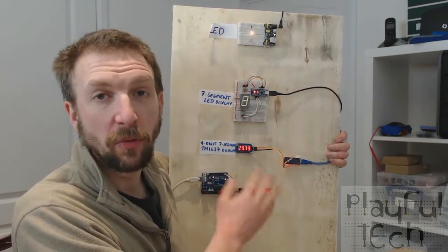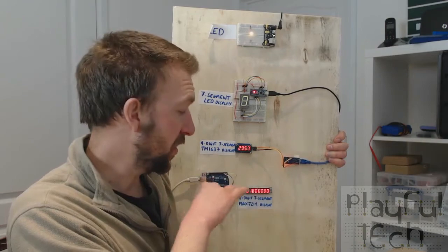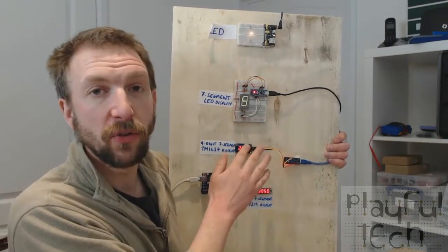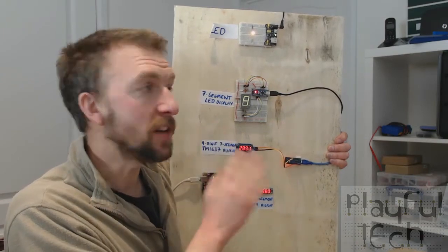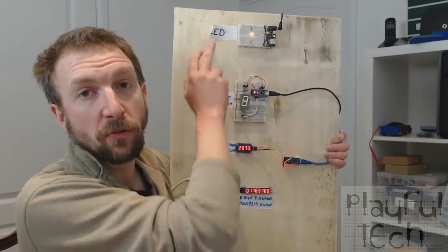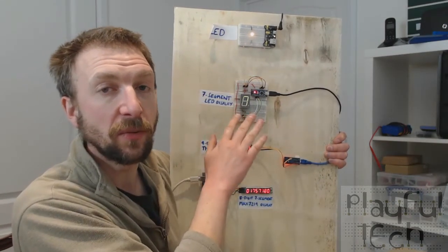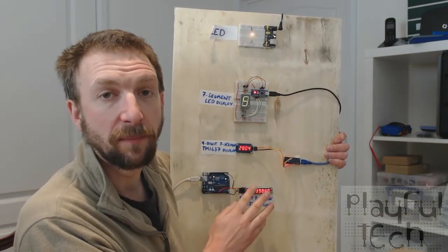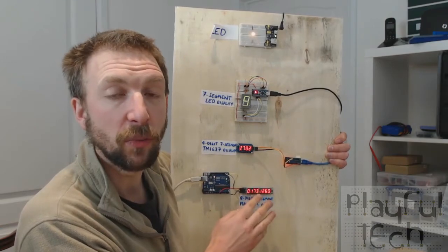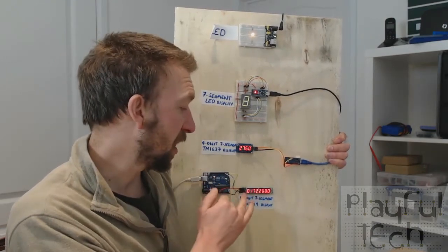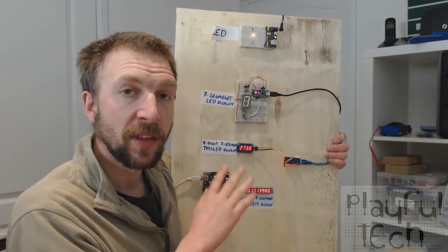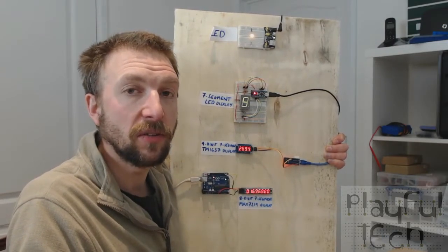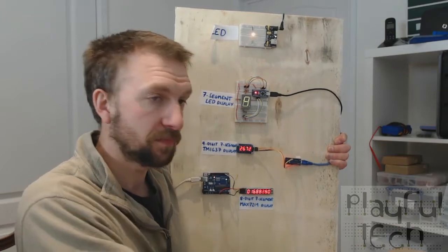So in a strange way, although these modules at the bottom are more complex in some ways, and they're certainly more flexible in what they're able to display, the hardware is actually much simpler. You either need 5 wires or 4 wires in this case, and you don't need to bother with the individual resistors on each of the LED segments anymore, because that's all integrated into the back of the module here as well. So the wiring becomes much simpler. And the code is actually not too bad either. So let me show you the code for these examples.